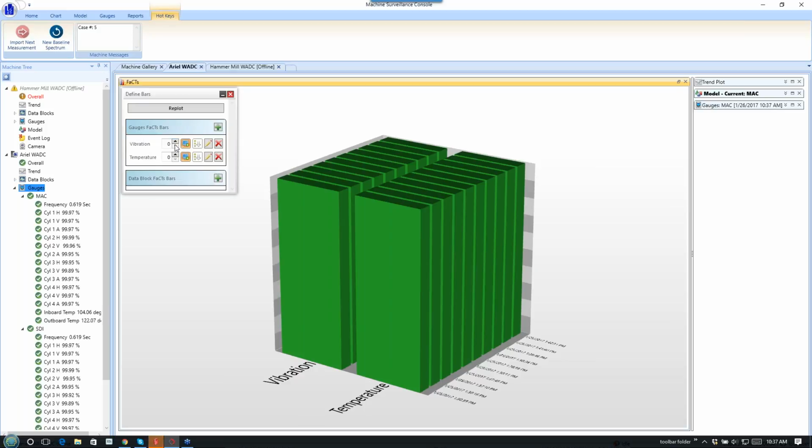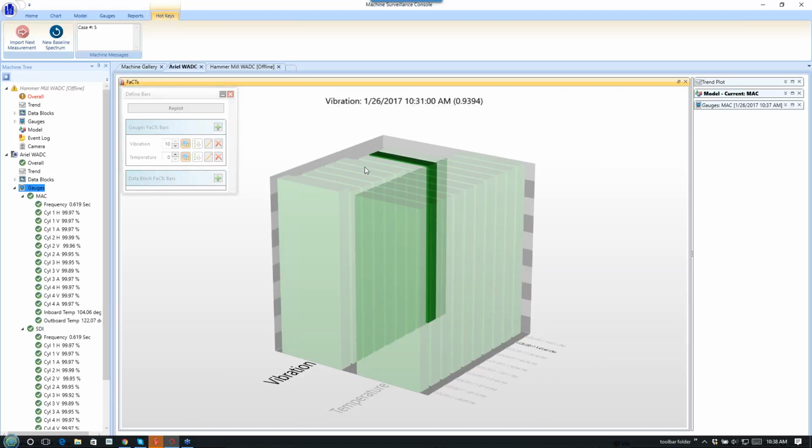Now let's go to this measurement. Let's go to our vibration here. You can see what it's using to calculate SDI, and let's crank the sensitivity. I'm going to crank it all the way to 10. Now remember what sensitivity did from our slide. That moves all of the shape values closer to 0. And that will make that SDI calculation much more sensitive. Let me update this. Okay, it didn't change a whole bunch, but you can see